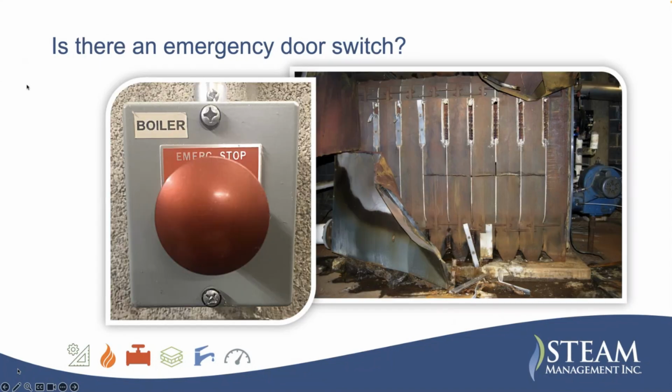Is there an emergency door switch? These are part of the ASME CSD-1 code, and these are awesome. I mean, I recommend these highly. If your boiler doesn't have it, I would urge you to get them in there. I'll give you an example of why it's so important.